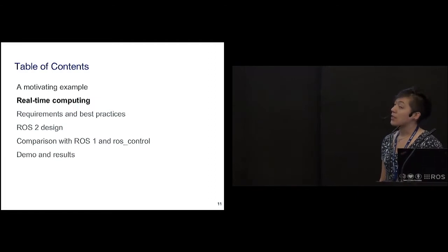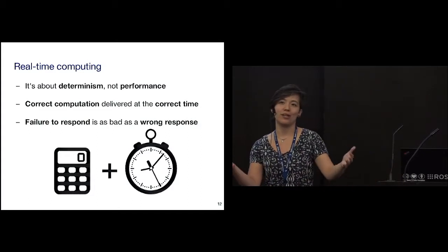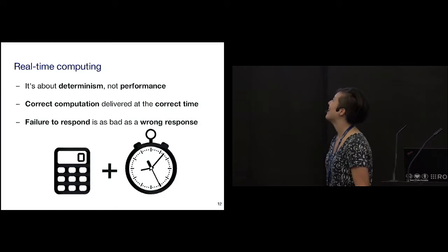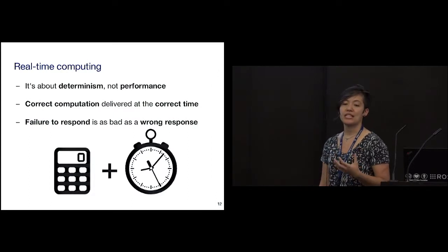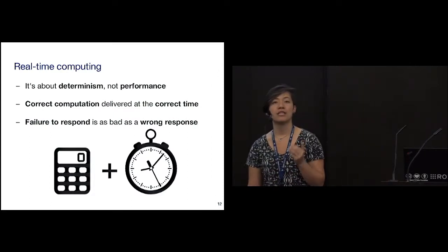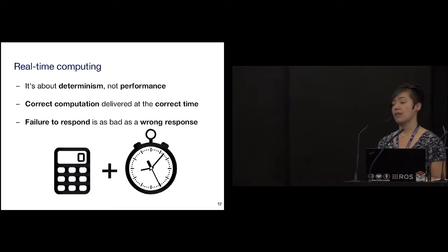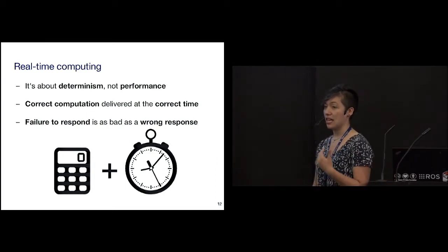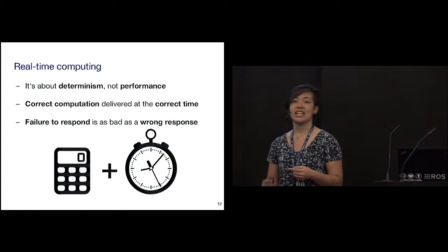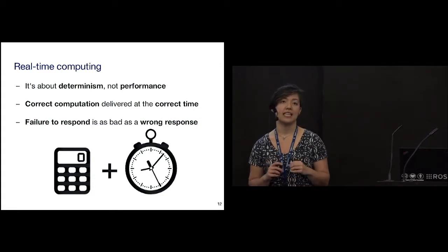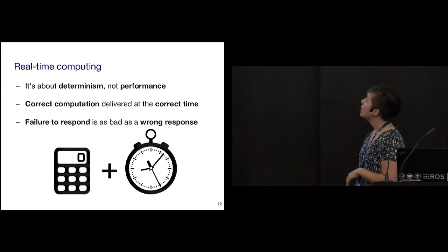Cool. So you guys apparently all know what this is, so I'm just going to skim through this so we're all on the same page. Maybe our remote viewers don't know, or someone's consulting this talk to learn about it. People often conflate real-time performance and low latency. But the definition of real-time performance is that you're deterministically meeting a deadline, and if you compute something after you've exceeded your deadline, then that is an error, or that is incorrect data. And often latency and real-time performance are actually at odds, because you may need more time to deliver the correct data. If you're trying to get a low latency system, you're going to exceed your deadline a lot.